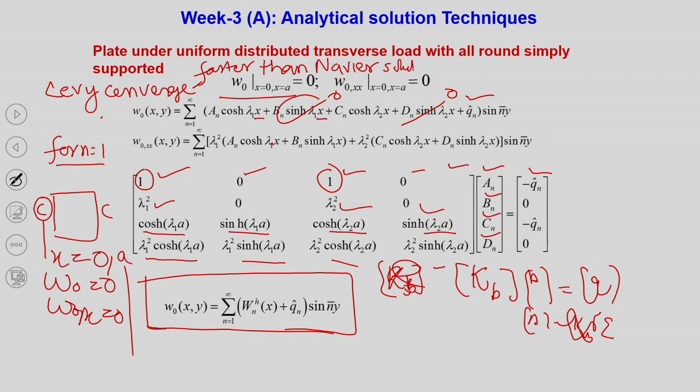One can verify it anytime, and it is beautifully given in the K. Chandrasekhara book, how many terms. You require only 10 terms. When you go for a Navier solution, you may require 21 terms or more than that.